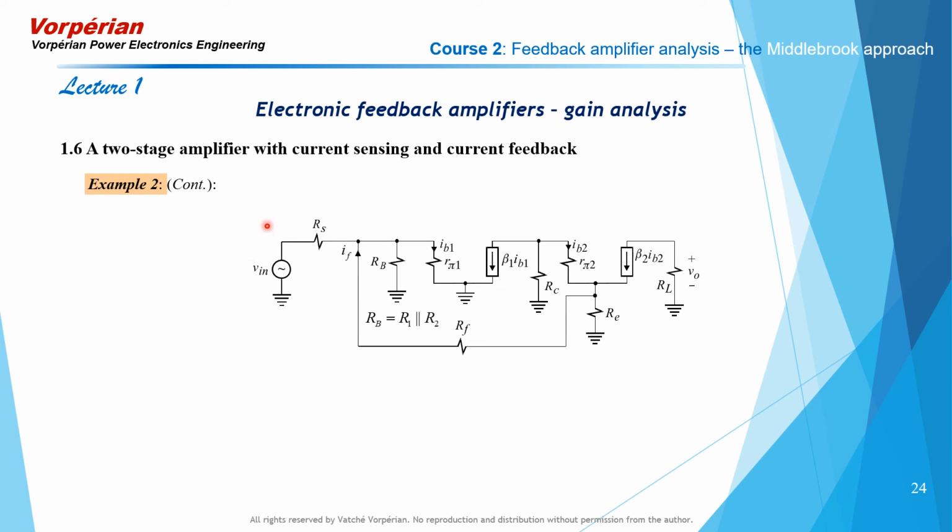Here's then the small signal equivalent circuit model of our feedback amplifier. Very much the same as the one before. And this is the feedback gain formula for the closed-loop transconductance. It is the ideal closed-loop transconductance with beta 1 equal to infinity, followed by a correction factor in which script beta 1 is the null inverse gain with respect to beta 1.